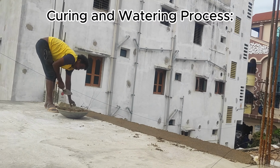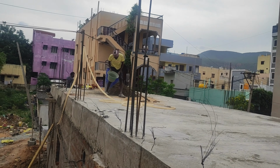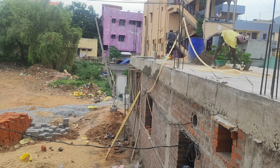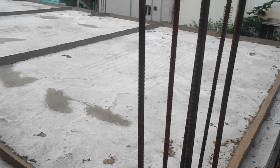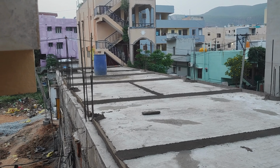Curing and watering process. Once the slab is completed, the curing process begins immediately to protect the concrete from drying too quickly and developing cracks. Curing is essential for strength and durability, as it allows the concrete to hydrate and gain its full load-bearing capacity over time.